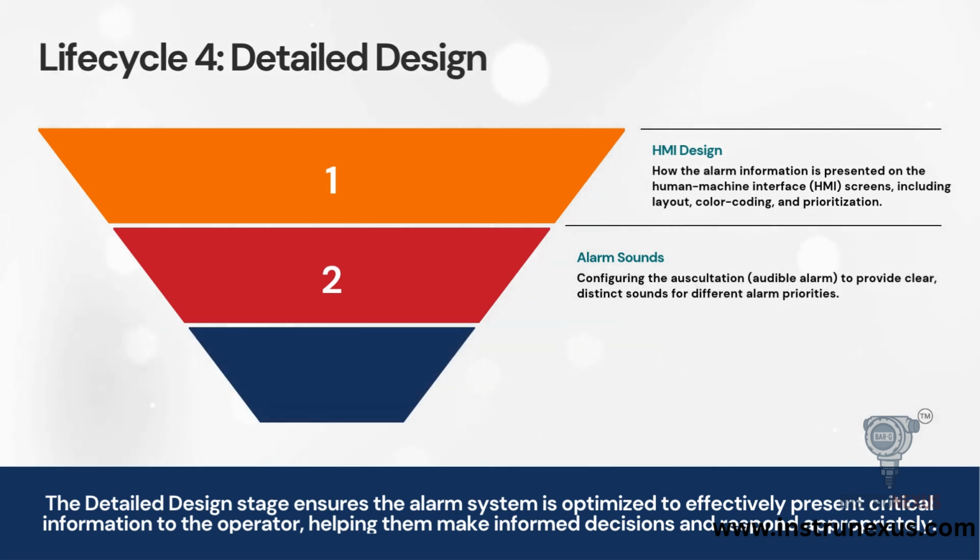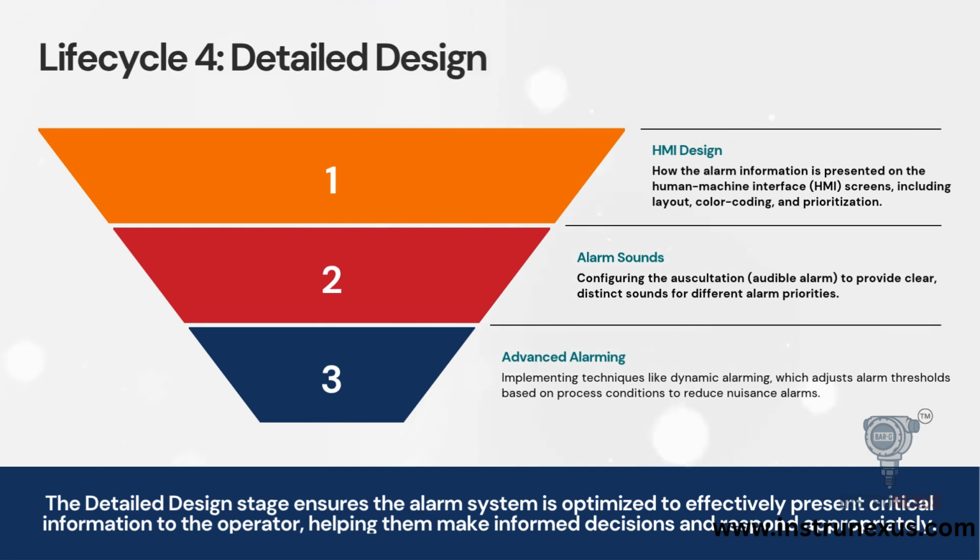This stage also involves advanced alarming techniques, like dynamic alarming, where thresholds might change based on whether the plant is starting up or in steady-state operation. The goal is to optimize the presentation so the operator can make informed decisions instantly.